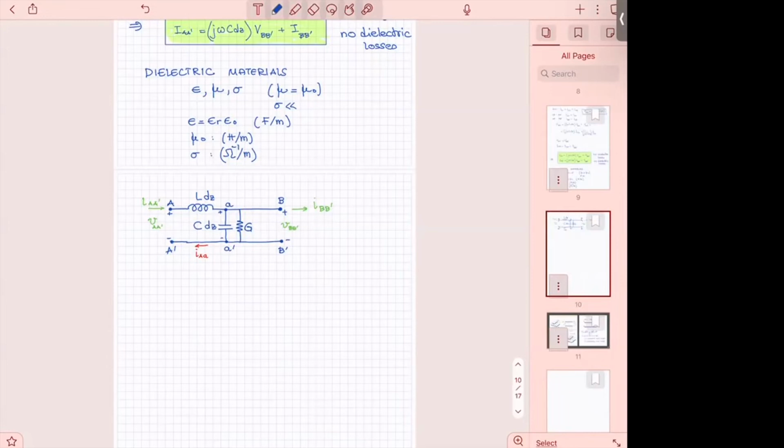And what value of a conductance, which we also saw like this, all right? What value of a conductance G gives 0 current? Resistance. What value of a resistance gives 0 current? It's like an open end, all right? It's going to be open, which means G is going to be 0, all right? Do you remember that? A 0 conductance means no current. Why? Because a conductance is 1 over resistance, all right?